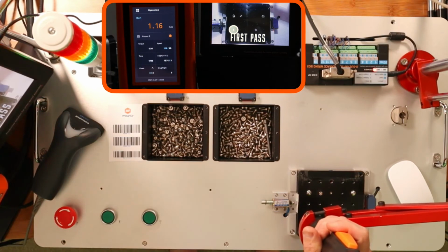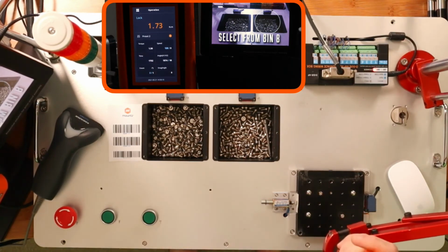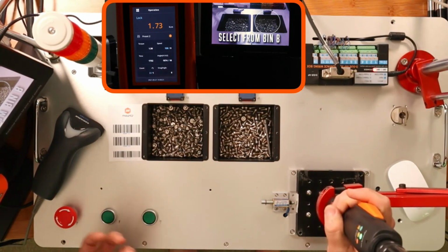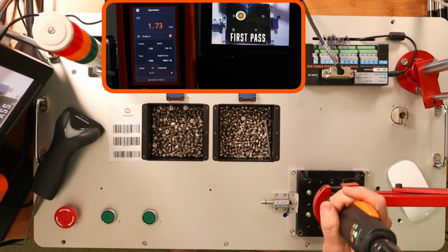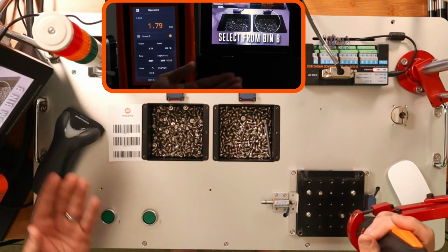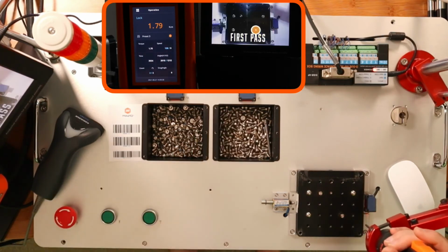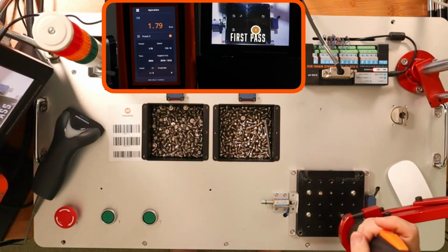The light has now turned green. And not only that, but we actually changed to a different preset. So now we're using preset 2 for that fastener. When we move to our next fastener, we should go ahead and get a preset change as well. So now we're using preset number 3, and we can run this down, and this will then go ahead and allow us again to have power to the tool only when we're in the right spot.